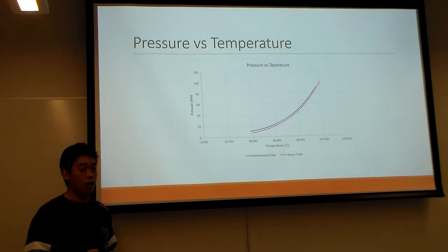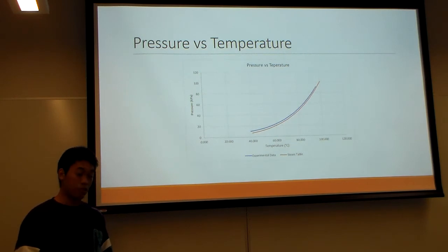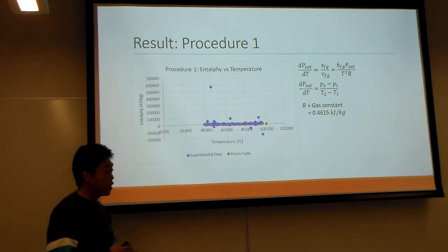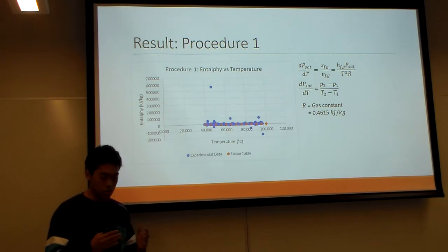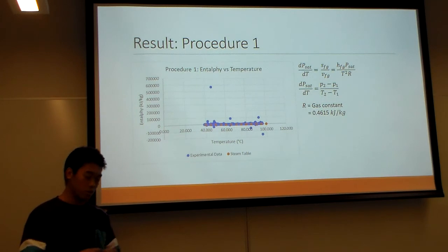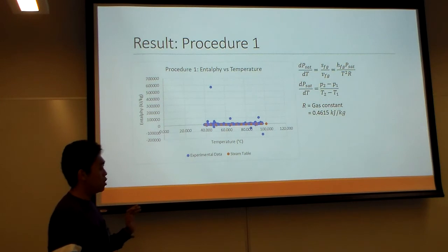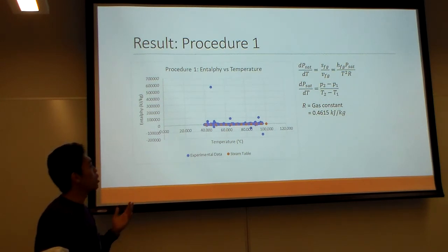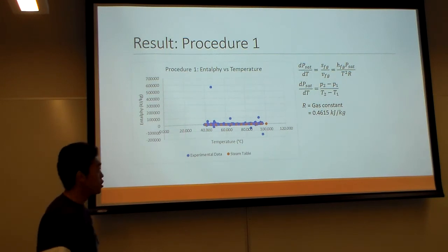And using the Clapeyron equation, we can find the latent heat of vaporization of water by finding dP/dT with three procedures. The first procedure is finding the local derivative of the pressure, where finding dP/dT is just the pressure difference divided by the temperature difference between one state and the other state. However, it's not convenient to use, since this causes a lot of error and also a high range of error, which needs to be reduced.